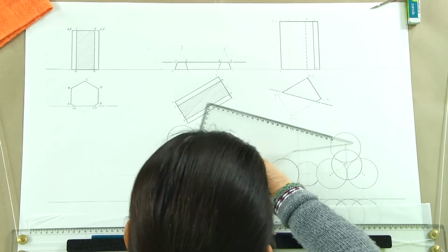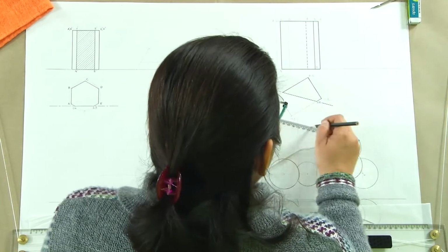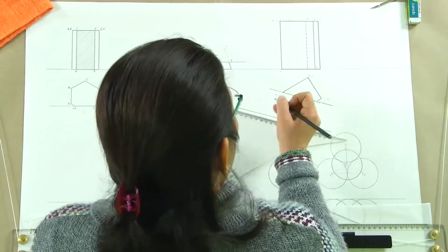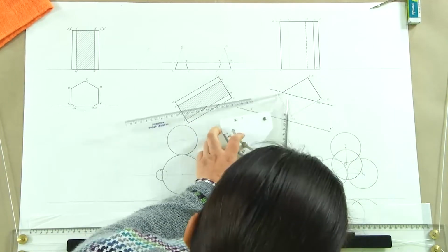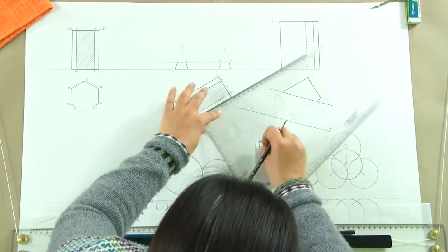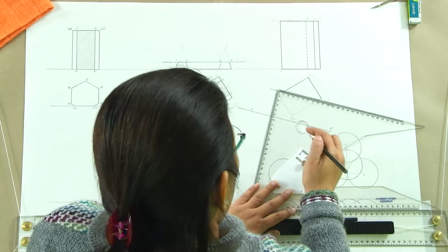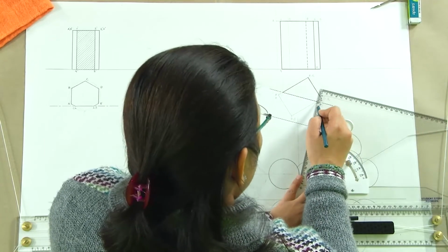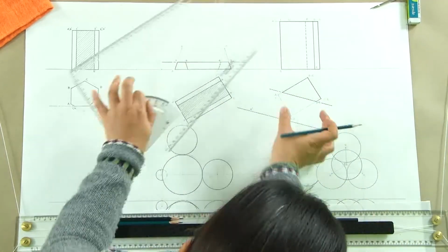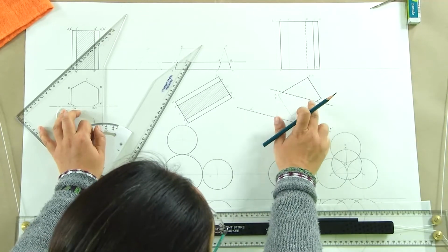So, let us draw a reference line XY which is parallel to this section plane. So, assuming this is our reference line X dash Y dash. Now, since it is parallel to this, if we take the projections of this section plane onto this, it is going to be the actual width or actual dimension of the section.